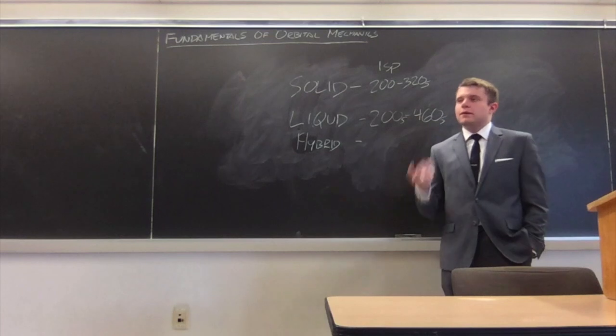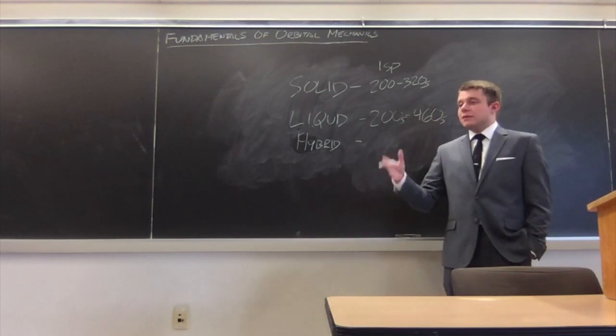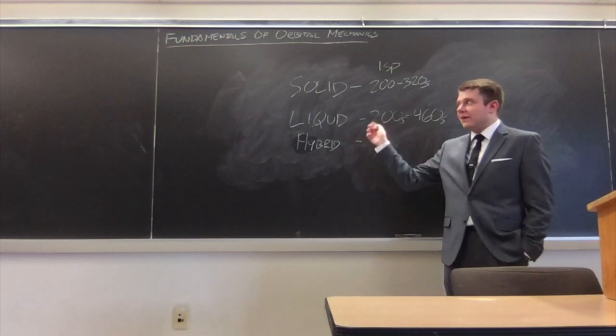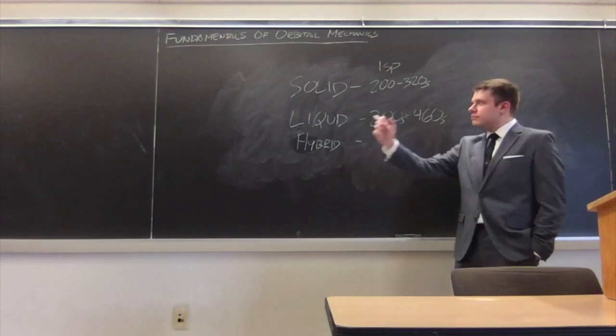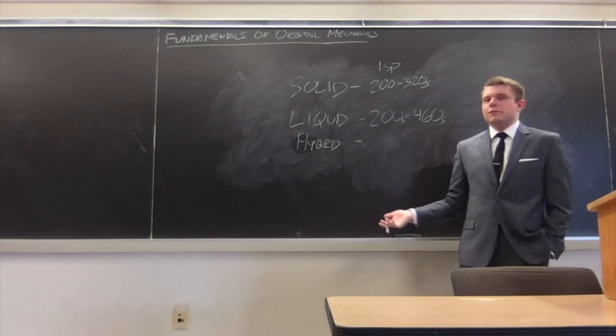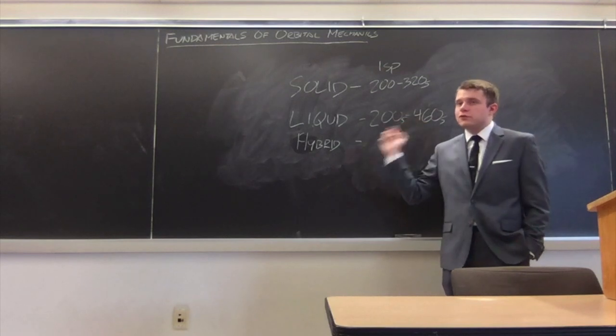So when you spark up the igniter, they combust, they get a self-sustaining burn going, and you make sure that the combustion is actually stable. It's a lot harder to do in a liquid motor. So they have a lot of advantages, but a lot of disadvantages. And that's why most rockets in the world today use liquid motors, because people are willing to put the development effort in because the benefits are so strong.